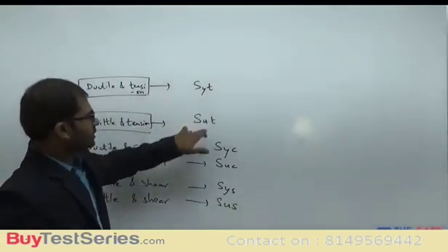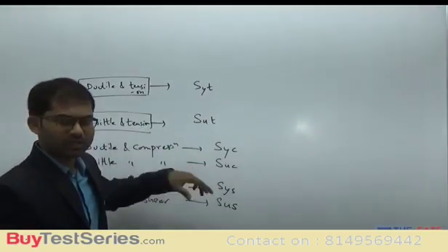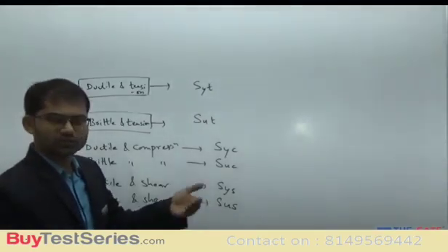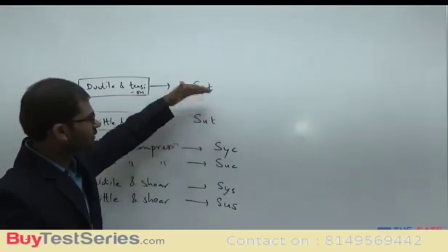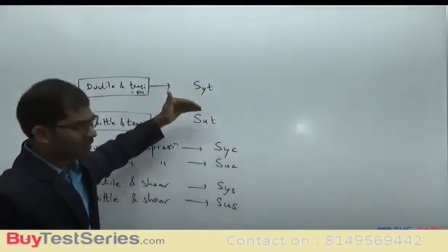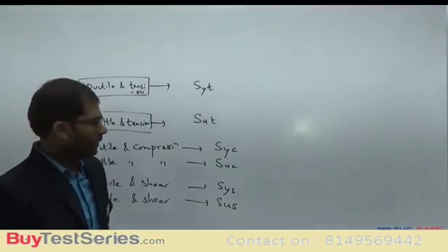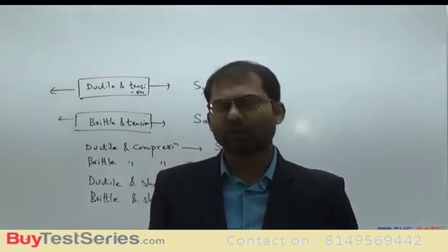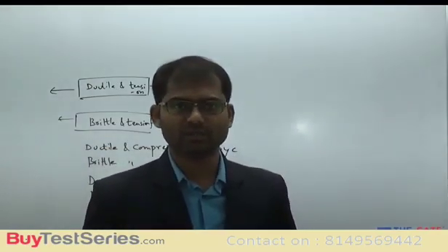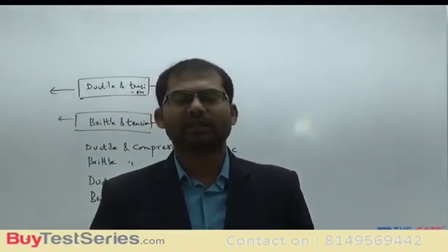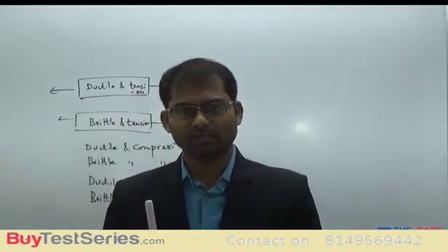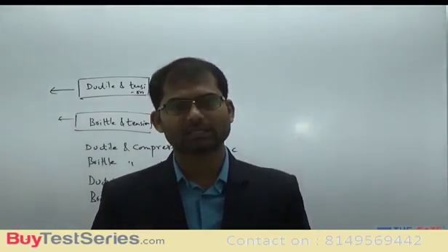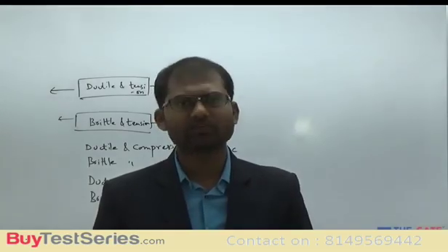So these values I can get by experiment. Once I get those values, I can decide whether the applied load or induced stress will cause failure of the material or not. If it is more than this value, failure will definitely occur. If it is less than this value, failure will never occur. So in this case, we can easily say. In tensile loading, for example for aluminium, I will initially find out the value of strength in tension. If the load creates a stress more than that value, I will directly say that it's going to fail. If the load gives a stress less than the strength of the material, I will say failure would never occur. It's very easy to tell here.